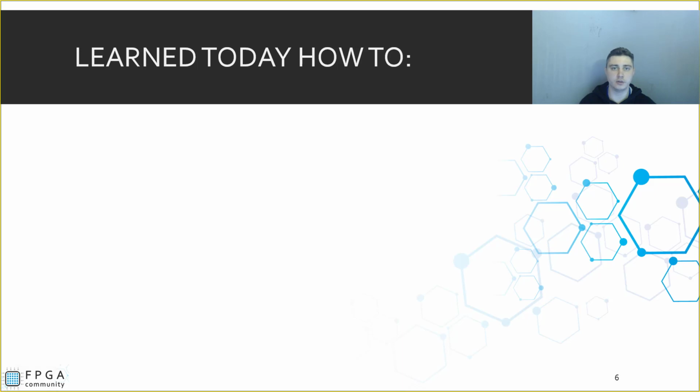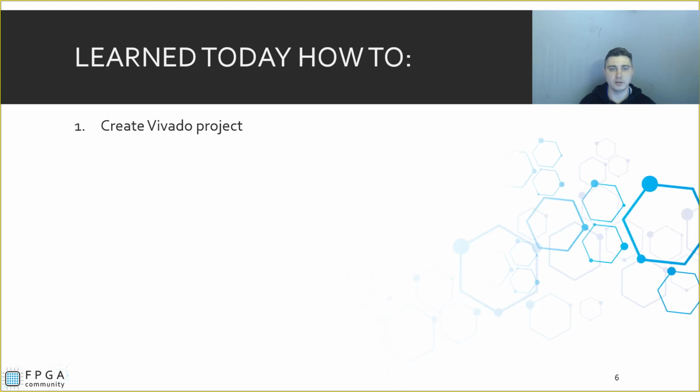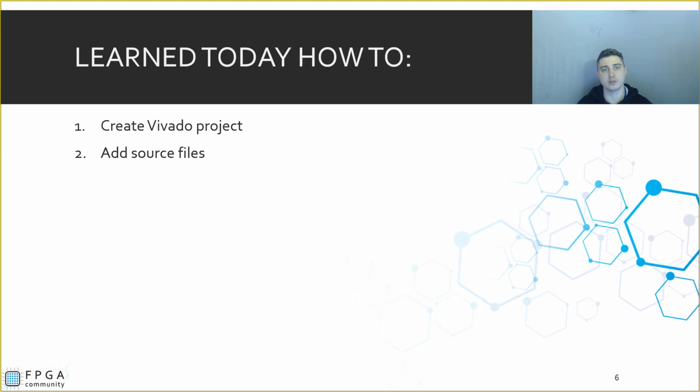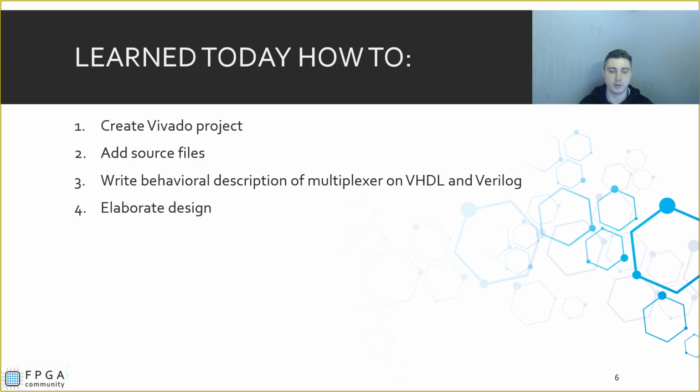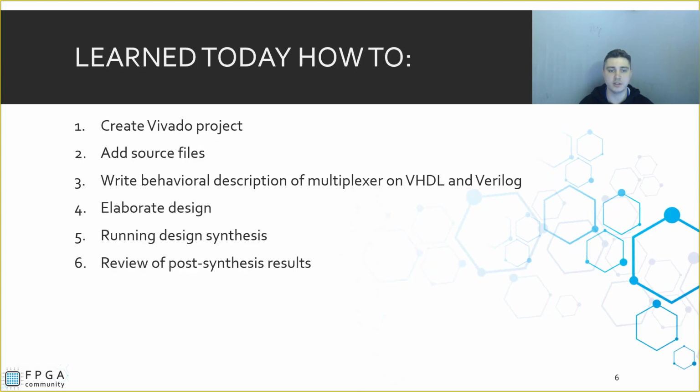Today we learned a lot of new things. How to create a Vivado project, how to add source files to our project, how to write a behavioral description of a multiplexer in VHDL and Verilog, how to elaborate a design, how to run design synthesis, and how to review post-synthesis results.